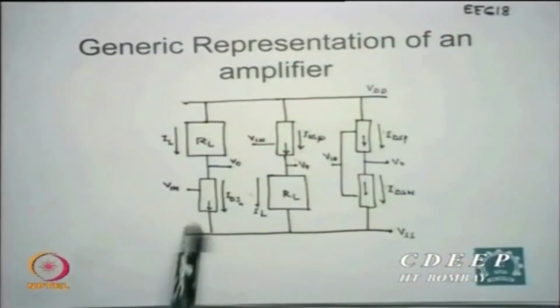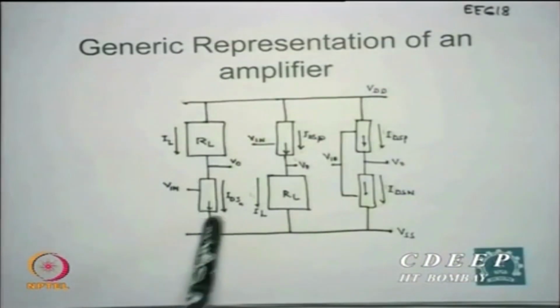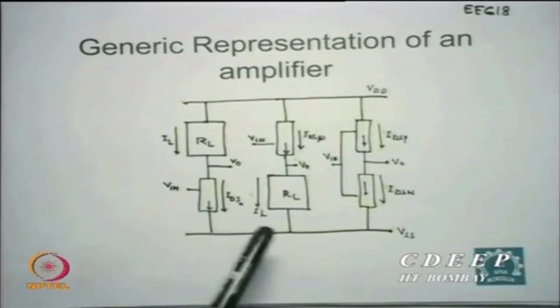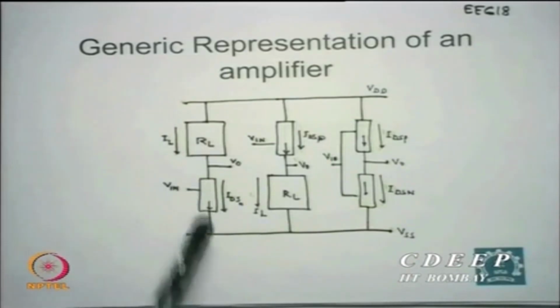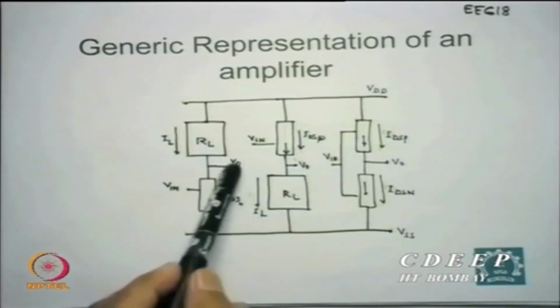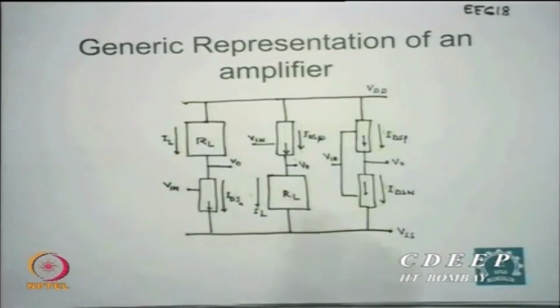However, here the circuits which I am showing probably have gains. There are three kinds of amplifiers shown by me. One is a standard amplifier which all of us know. So these are three amplifiers shown here. The first one which you are seeing here is essentially an amplifier in which there is some kind of active device. In general it may be an n channel MOSFET which has an input and it allows some kind of transconductance at the output. So it converts this voltage into some current, and through this load, current flows.